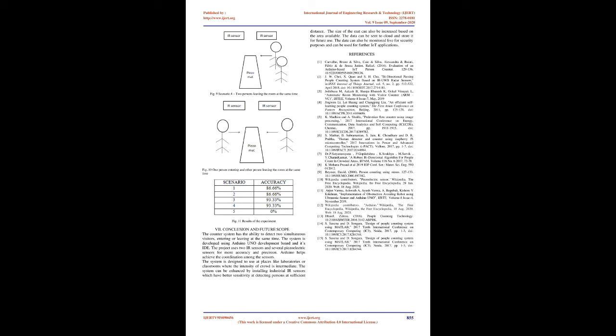When a person enters and passes through the mat, the weight of the person, which is in the form of external stress to the piezoelectric sensor, is converted into an electrical signal. The electric signal is greater than a certain threshold, and the digital output is high. The threshold value is set so that whenever a person passes through the mat it records the signal and the value is high for a certain period of time.